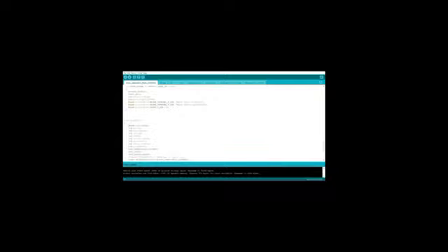In the setup we will always declare the init methods, and in the loop we'll always call the method that is already declared. In ldr.cpp, we are declaring the brightness control method, which controls the blinking of the LED with the help of the LDR. In ldr.h, the header file, we have declared the macros, the LDR sensor and its value, and we have also defined the methods.